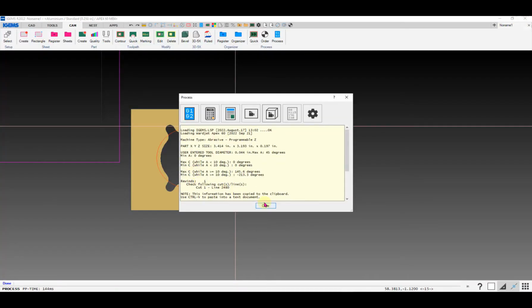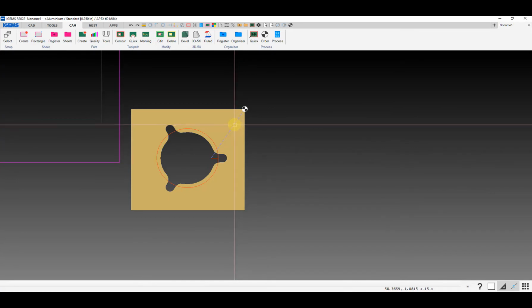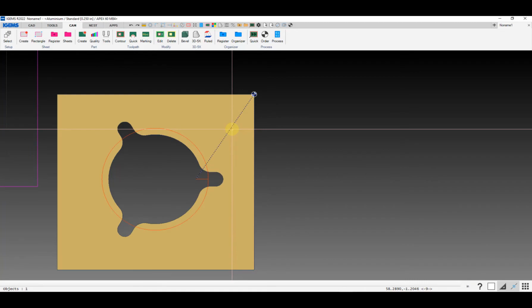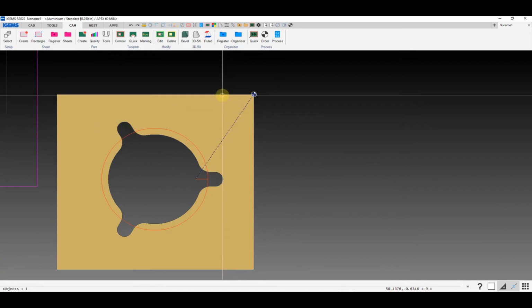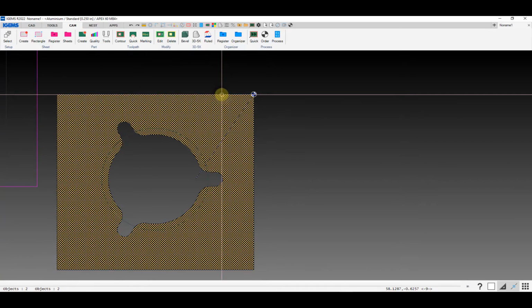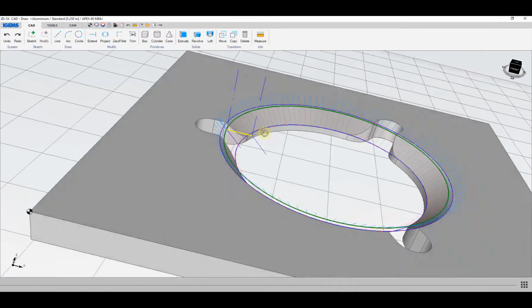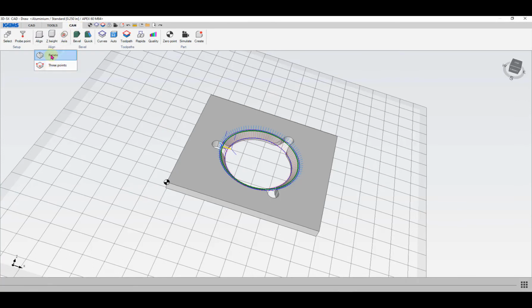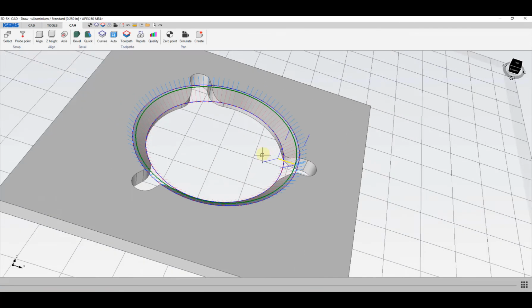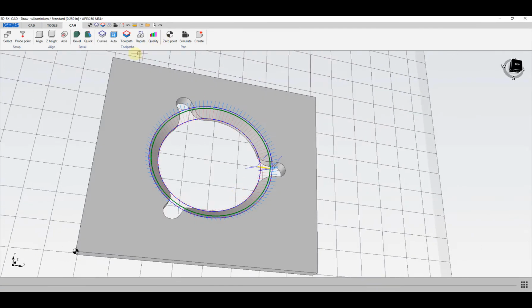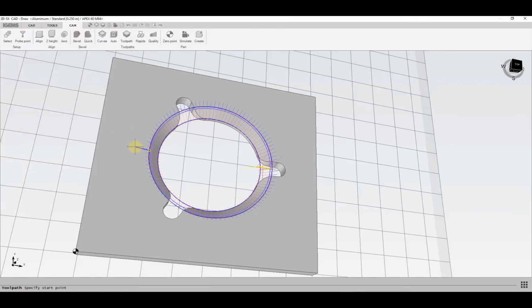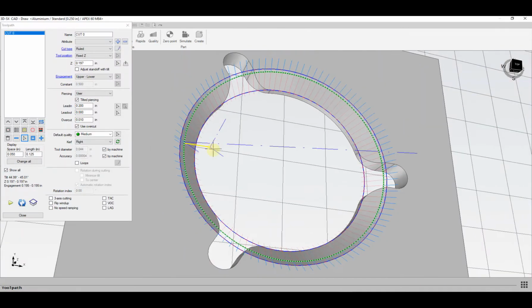So that's rewind. So again, to fix that, if my part were already programmed in this orientation, then I could double click on there and change the part in 3D5X. Of course, this is the original orientation of that part. But if I rotate it in here 180, so this orientation would give us that rewind, then I would come in and again use this pick button and put my lead in somewhere over here and avoid that unwind.